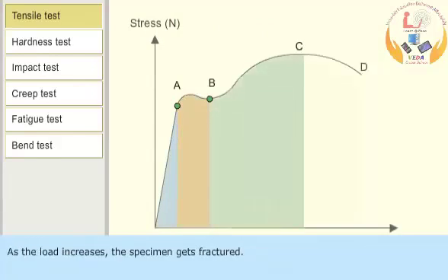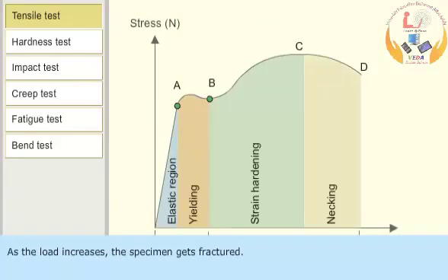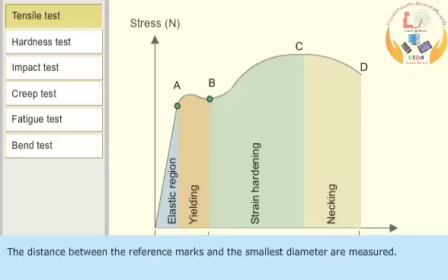As the load increases, the specimen gets fractured. After breakage, the broken ends are fitted. The distance between the reference marks and the smallest diameter are measured.